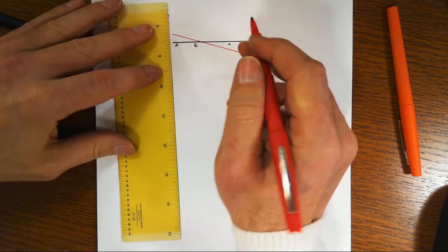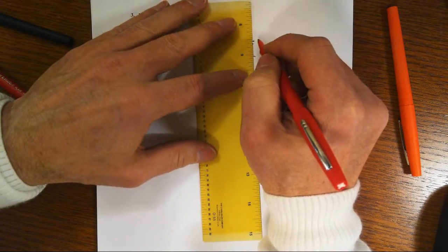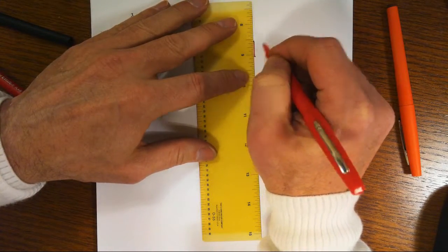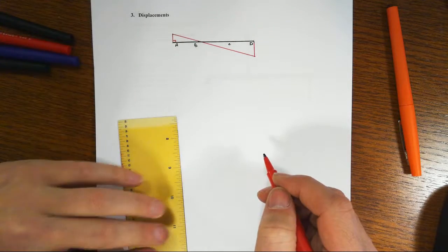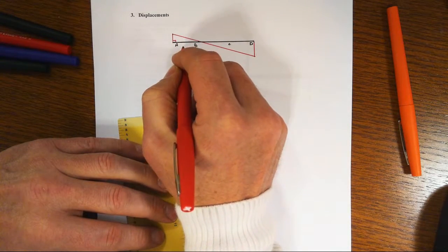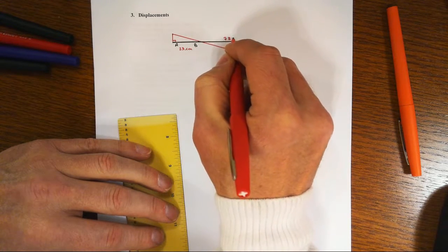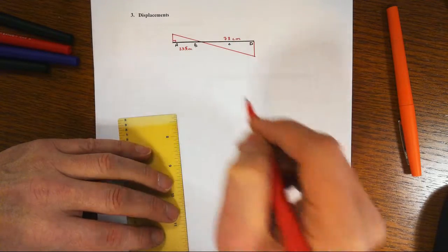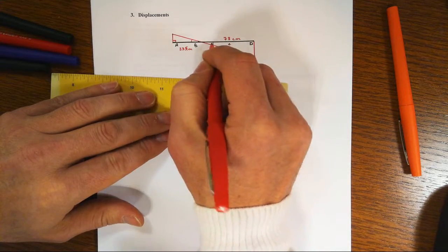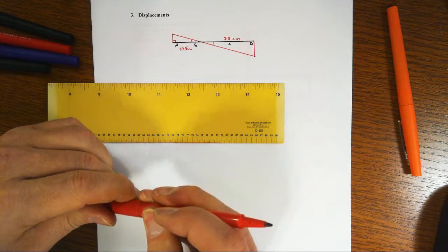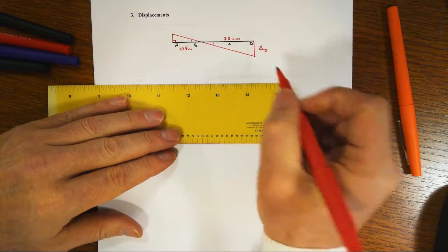And note that what we're going to do, even though each point is going to actually swing in an arc, these angles are actually going to be so small that we're going to ignore that arc, and we'll assume that this triangle is not really an arc, it's rather instead a right triangle. And we'll keep the original dimensions here along the base of these triangles. Yes, that is not exactly correct, but to a first order approximation it actually works out sufficient. And we'll see what the magnitudes of these are at the end of this and see how small this really turns out to be.